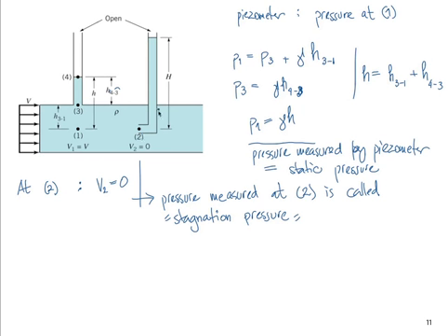And that generates a different height of the column of liquid there, if we were to build a piezometer here that turns and faces the flow. Basically, the flow pushes the column of fluid a little bit higher than it would be if we were just measuring static pressure here. So point 2 is also called the stagnation point.